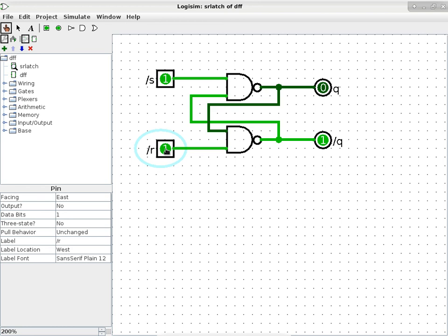In other words, if you switch both input pins from 0 to both 1s at exactly the same moment, and the gates have exactly the same propagation delay, then you observe the output switching between 0s and 1s. And the period of that switching is going to be 2 times the propagation delay of the NAND gate.